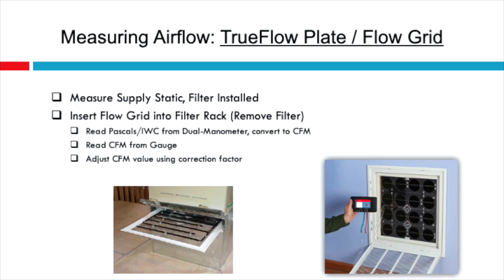So those first two methods I talked about were the least expensive and fairly repeatable. I would say static pressure is a lot more accurate and repeatable than temperature rise. This next method, if you have a central return or a return grill or filter that's close to the system, I would say is the most repeatable, no matter who is sliding the Trueflow Plate into the system.